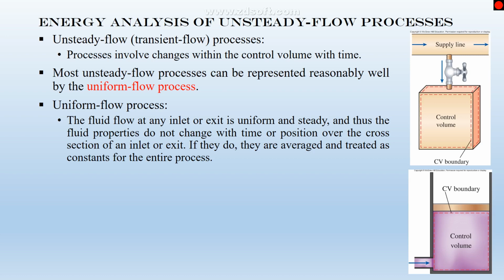In these cases, the total energy and the total mass of the control volume change with time. Correct? For example, consider this tank. This is during charging. It's connected to this supply line, and then fluid is added to this control volume. So the total mass of this control volume plus the energy of this control volume changes with time. So this is not a steady state process, it's an unsteady state process.